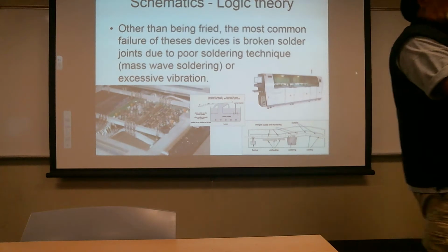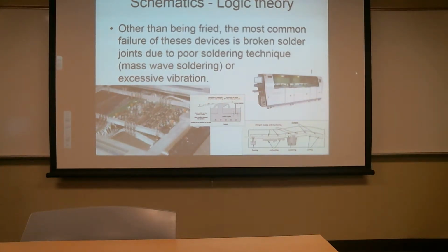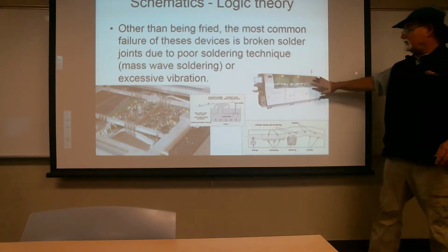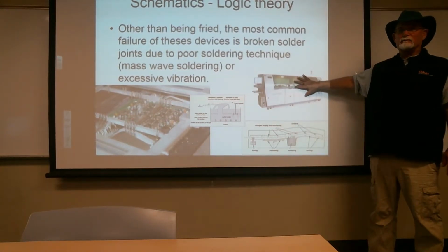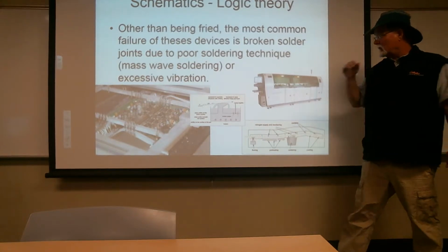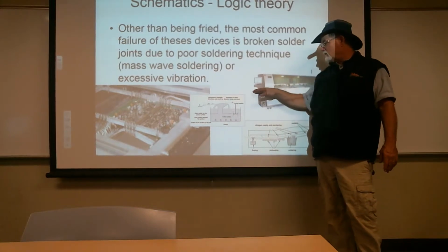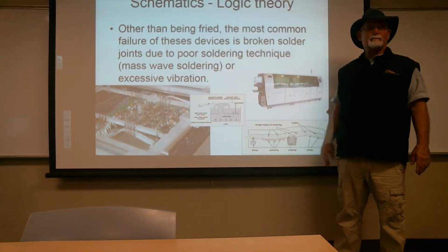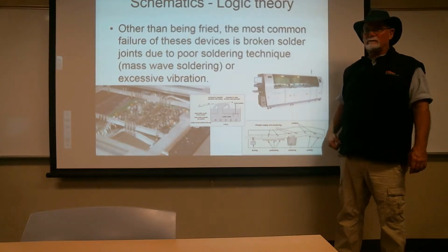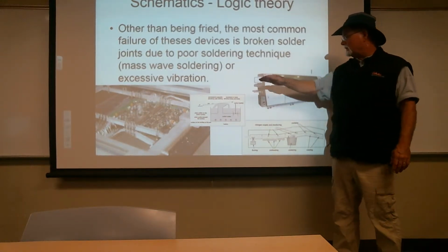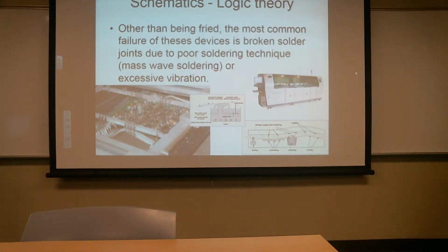If flux is needed, they're already pre-fluxed. And note that that wave of solder is staying nice and clear and shiny. It's not oxidizing at all. Well, if you look in here, that's because we've got it in an environmental chamber. Okay? And so what may be happening is, this isn't connected to the rest of the manufacturing process, but it comes into here through a little induction chamber. It's a little atmospheric gate that allows each board to come in, moves into the atmosphere controlled environment.